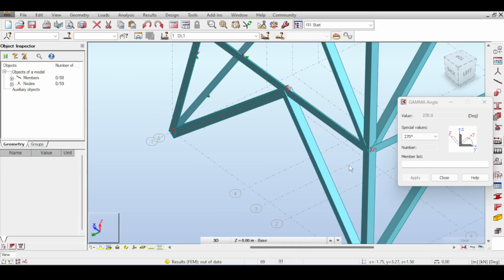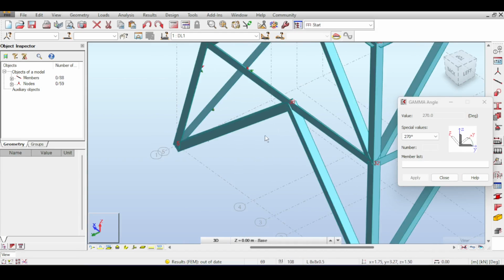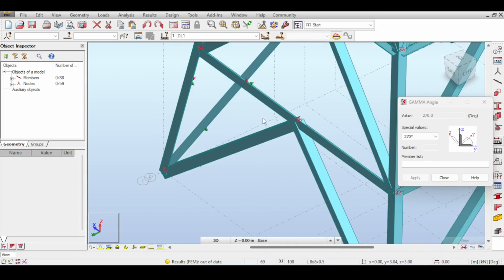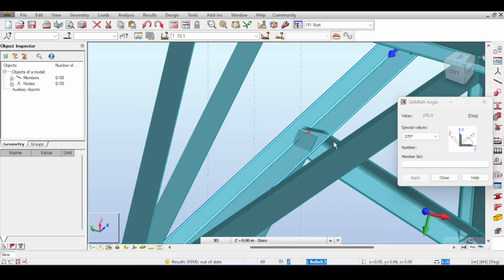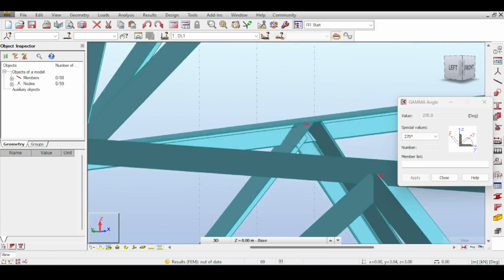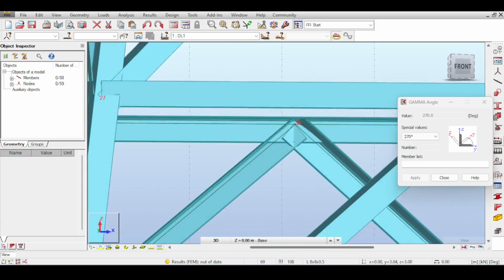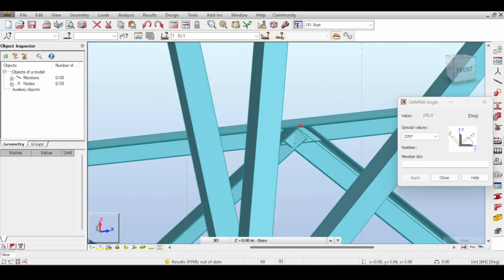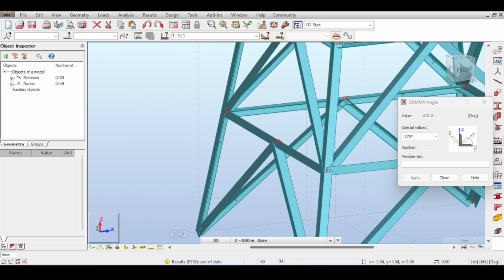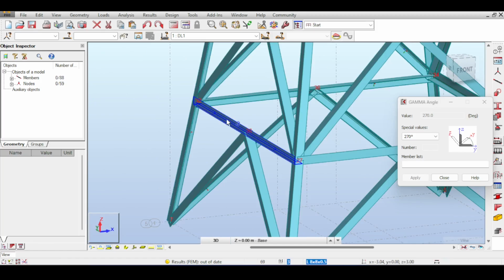So after a grueling task, I was able to rotate all those diagonals, to draw the diagonals and rotate them. But there was one thing. You see, this doesn't seem right. This connection in real life is not easy to achieve. So if I rotate this, now this becomes feasible. You can easily put a pin here, a bolt here, and finish the job. It's kind of annoying, but you have to take it into consideration. There is no escape from this.